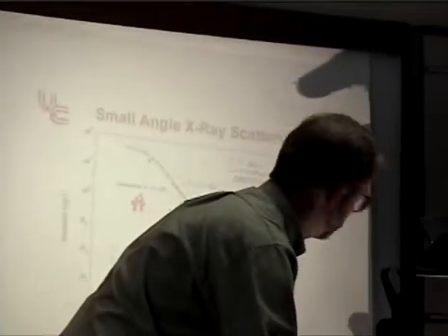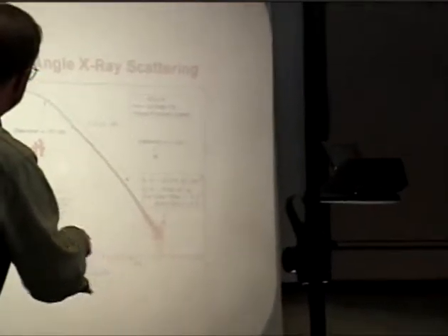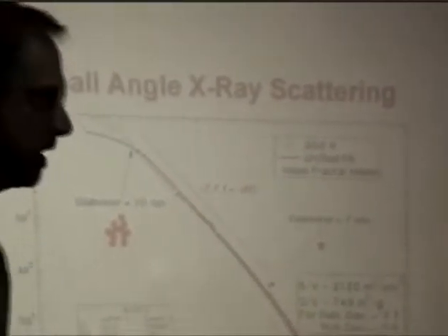And this is a typical fit to one of these structures where we have the primary particle size, 7 nanometers, aggregates roughly 10 times bigger than that, in a fairly high dimension, indicating that it's a reaction limited process. So it's a denser structure because the particles bounce around and they pull in. The materials have fairly monodisperse pore sizes.